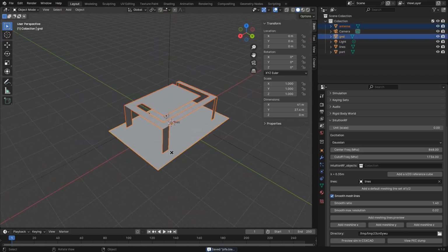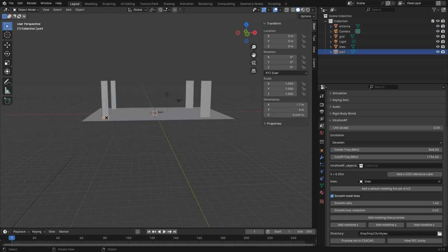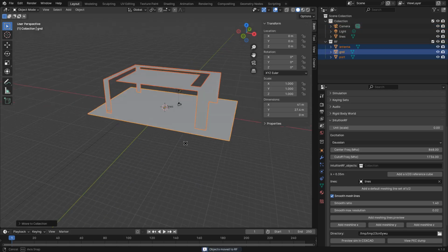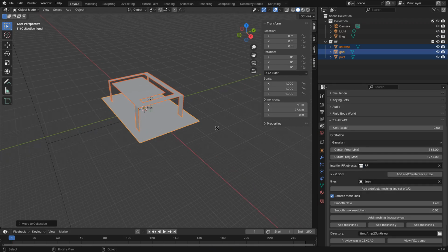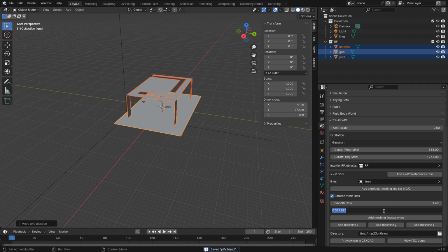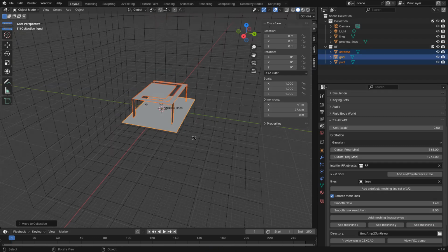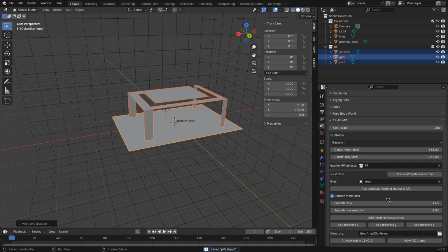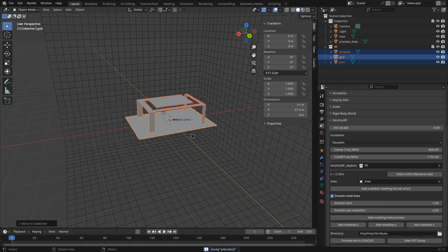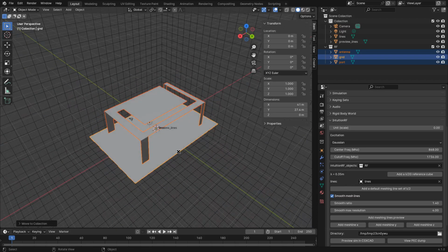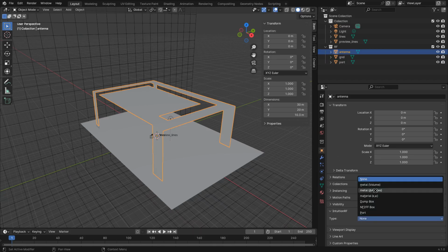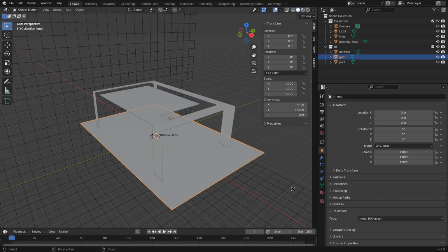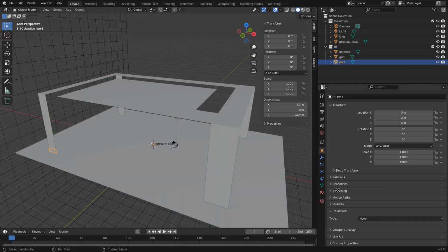Now I am going to make a new collection for the RF objects, like this. Set it here, set the resolution way up, and show some meshing. Okay, let's go with 4, like this. So that's our antenna model complete. Let's make the top antenna a metal with axis-aligned faces, same for the ground plane. And let's set the port.